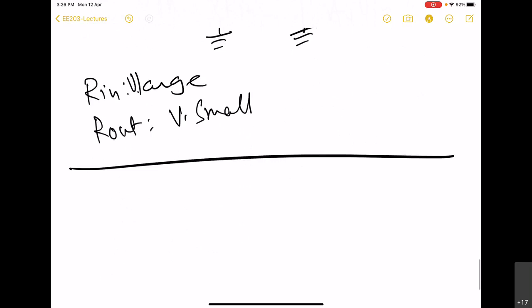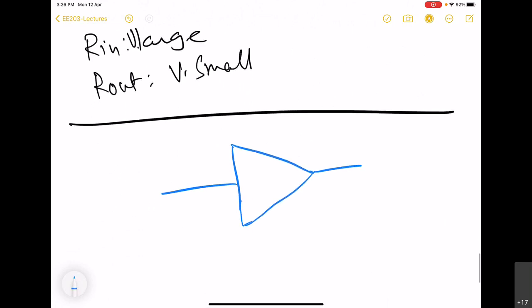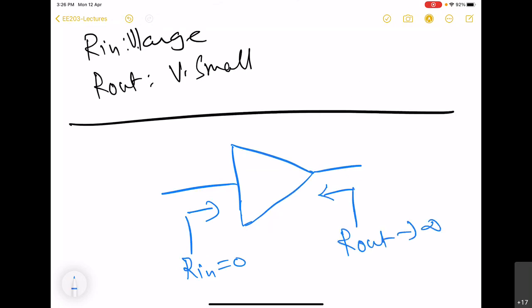Now we are going to take the second type of amplifier. In fact, it will be the fourth one that we pointed out, because that represents entirely different input and output resistance conditions, that we now have R in equal to 0, but R out is infinite. And as was pointed out, we will be designating its transfer function as AI.